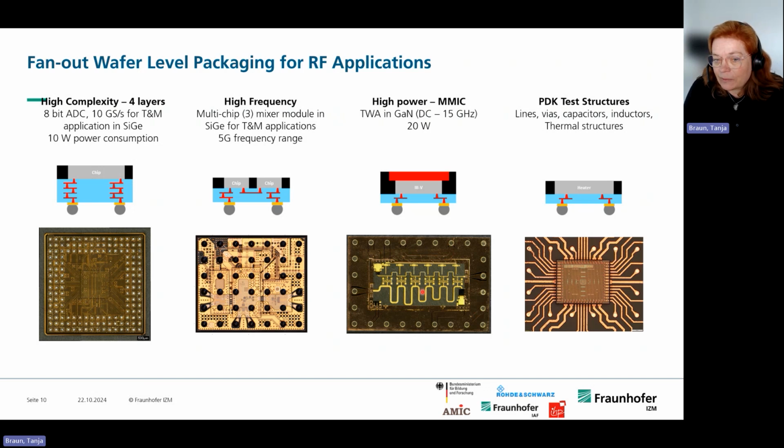And in addition, of course, there might be a lot of heat generation, so you have to carefully work on concepts for how to get rid of the heat, so you need heatsink embedding and so on. But this is maybe one very nice topic where we have already built packages with GaAs and GaN dies, with GaN and silicon dies, and maybe even add, in this case, passive components as a component itself in the package.